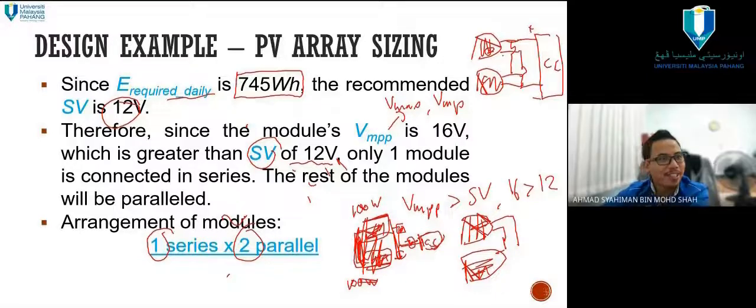Dah hampir betul tapi terbalik sikit. Okay. When we do parallel connection, sorry lukisan yang bawah tu agak buruk, mengelirukan. When we do parallel solar panel, our panel voltage will stay the same lah. Make sure we need to use the same module, same rated module. Don't use different. If you use different, then dia akan confused sikit.